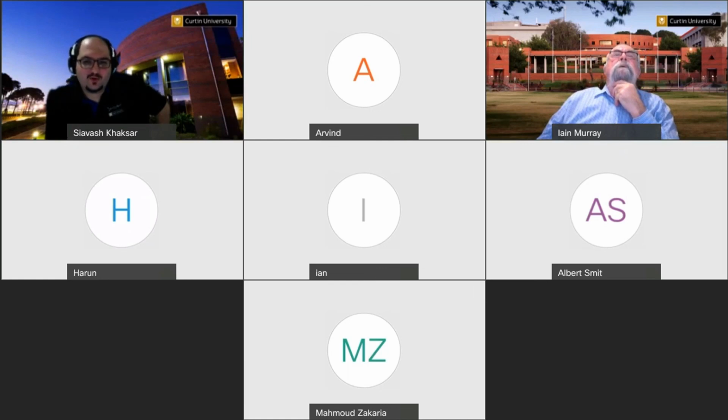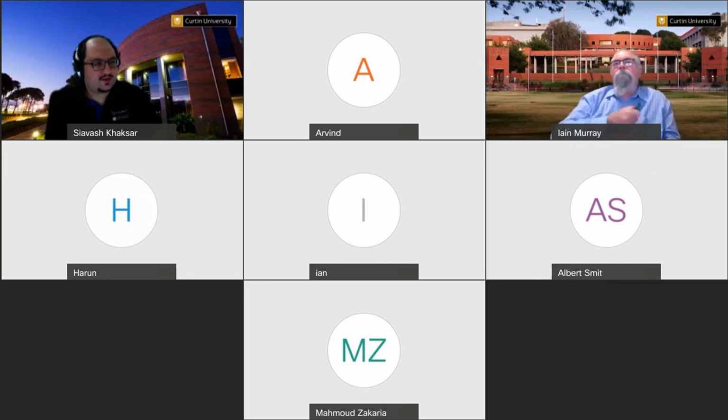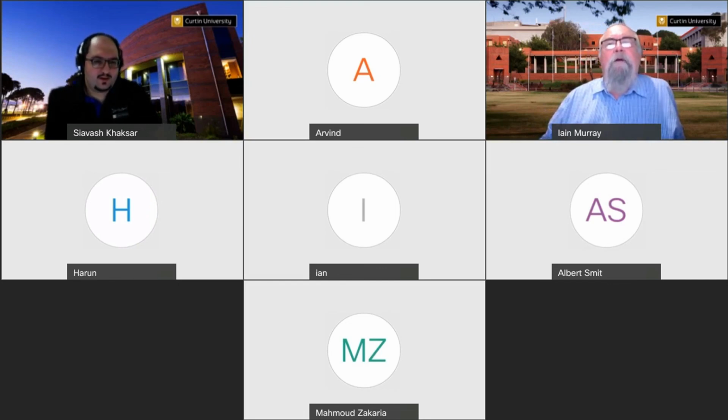Well, you could. Arduino does provide the specifications for the board you're talking about, but that's probably overkill. I know the board you're talking about. That's the one we were initially using because it has enough processing power to do the three-phase audio detection. I was just thinking maybe you can get the guts of that, remove the peripherals that you don't need, and just keep the essential processor. It would be the same processor, so it would still support the library. Maybe if you don't need the Bluetooth, remove that, and then lay it on the flexible PCB. There's also the option of transferring the audio via Bluetooth link and having the processing done in a unit you drop in your pocket or clip on your belt.